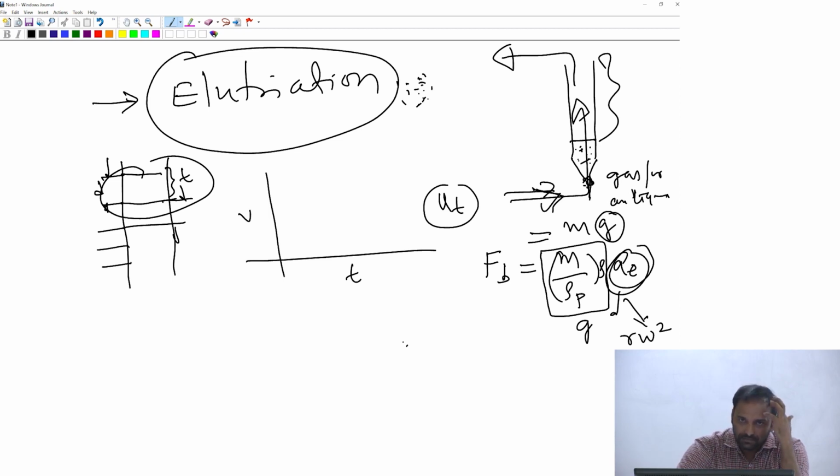Yes, it will, right? Because the plot that I showed for CD versus Reynolds number, it was written that it's only for a spherical particle case. However, people have done experiments on particles that are rough, irregular, disc-like particles, cylinders, and stuff like that. Also you would have to worry about all of that as well.